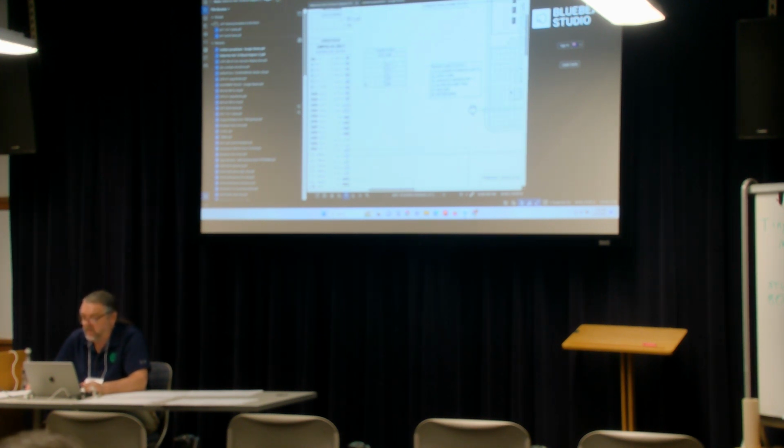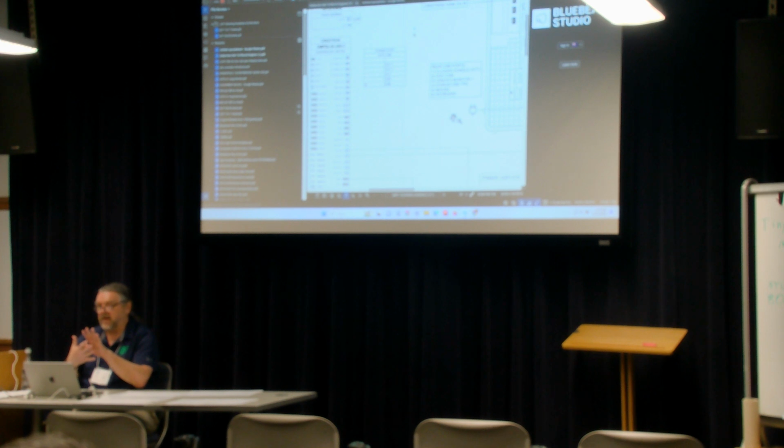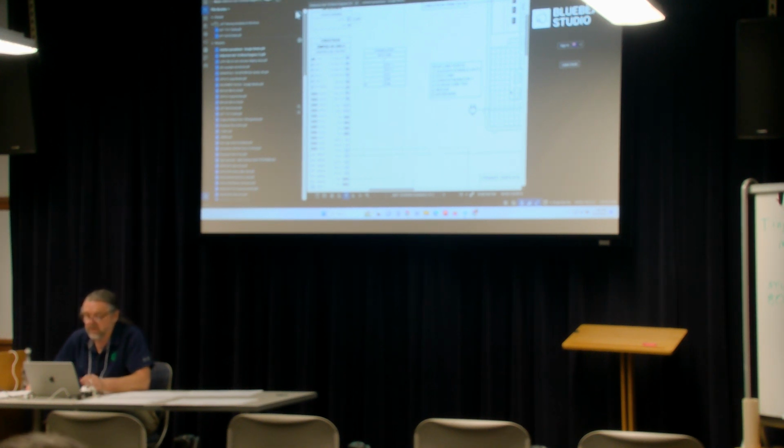Well, actually there are two ways to get rid of it. You could create a square and fill it with white, and you could turn your line to 0 point so that you don't see it. And then for all intents and purposes, it's gone. A better way to do it, because even though you can't see it, it's still there, is this: when it renders on another machine, you'll actually see it, and then you'll see the white block go over it. So the thing to do would be to erase what's there.